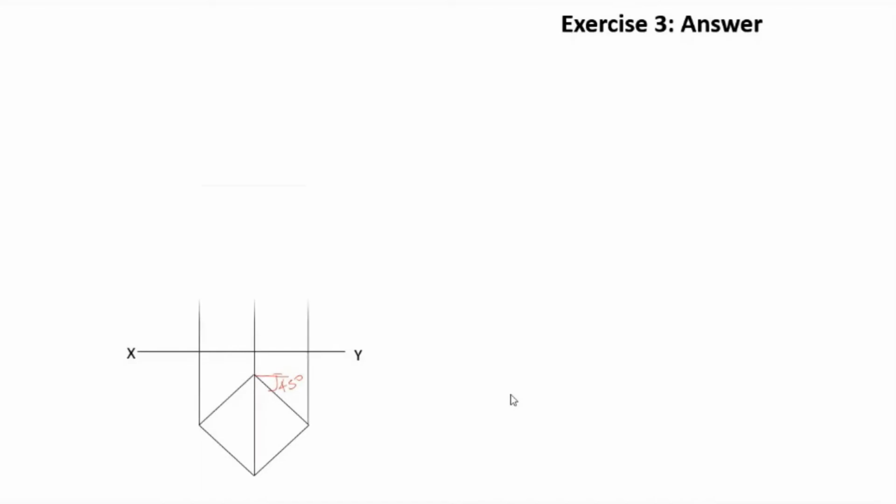Now the front view, with the axis length of 75 millimeter. Then all the points A1, B2, C3 and D4 in the top view give A dash, B dash, C dash and D dash in the front view, as well as 1 dash, 2 dash, 3 dash and 4 dash, out of which D dash and 4 dash are in the back.